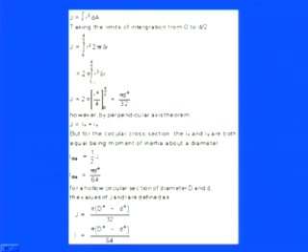So we have the integration from 0 to d by 2 of r cubed dr, since it is a cubic term from this multiplication. So we have r to the power 4 by 4 from 0 to d by 2. So the polar moment of inertia for a circular section is pi d4 by 32, and it comes from the perpendicular axis theorem.